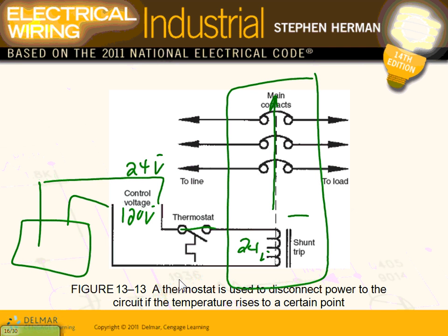Any question about the shunt trip? You get out of here, you work in any industry, guys, you're going to hear the word shunt trip all the time. What is shunt trip? Shunt trip is when you bring an external signal to a circuit breaker to trip it. There's another term, William, that's called closing coil, or motorized circuit breakers. With motorized circuit breakers, you can bring a signal and actually turn the circuit breaker on. Turn it on, not off.